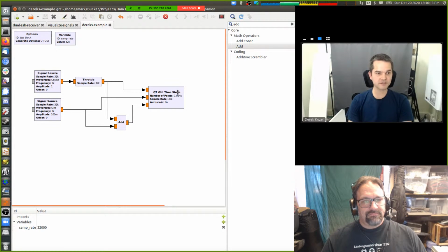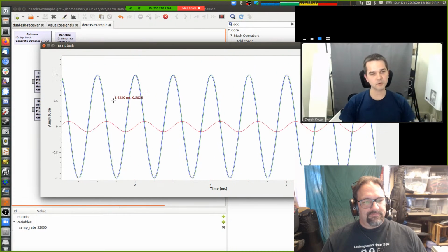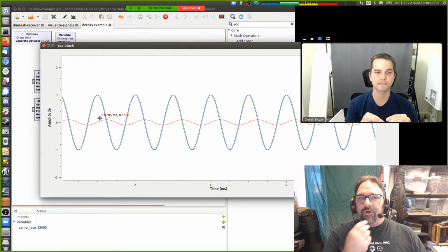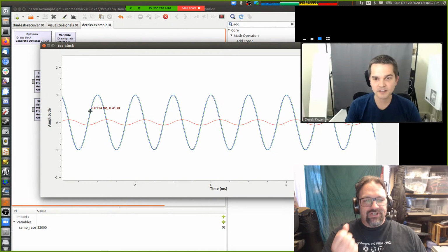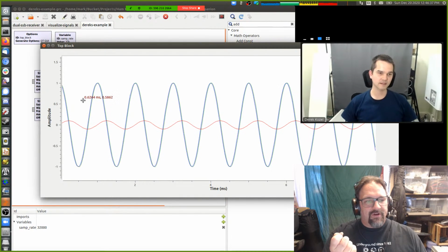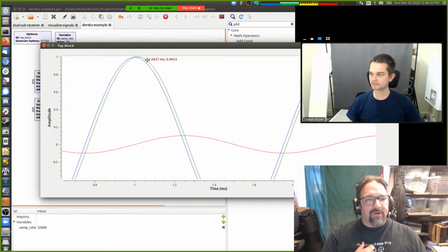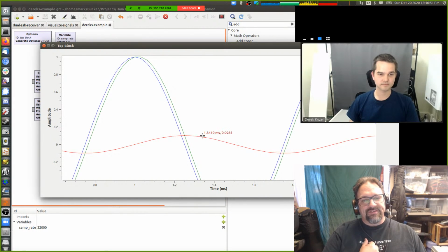So you're playing with different amplitudes, which is interesting. Remember, in an IQ signal, all you can play with is the amplitude. If you want to shift the phase of the resultant signal, the only thing you can play with is the amplitude. So what have we done here? Let me zoom in a little bit more. The green is the result. The blue is still our cosine. The green has been shifted a little bit to the right by adding a little bit of the sine.